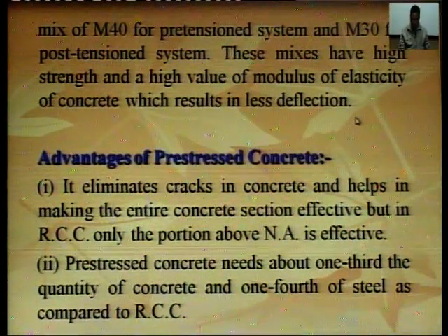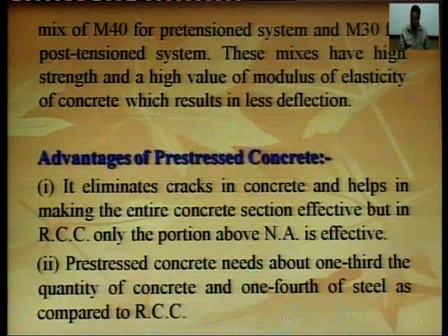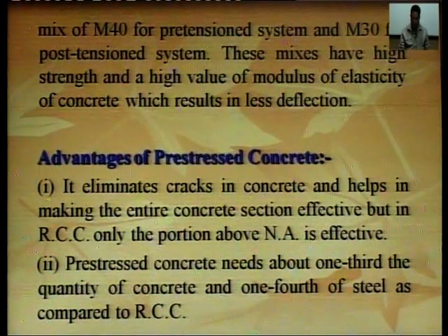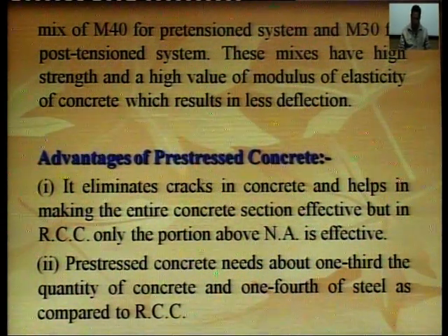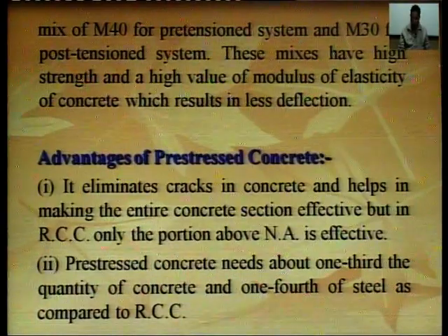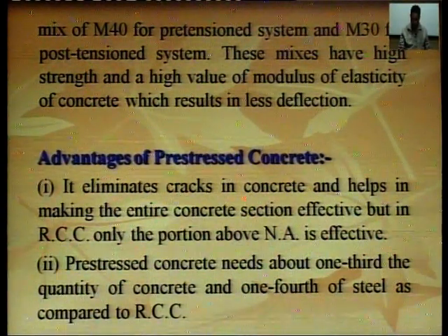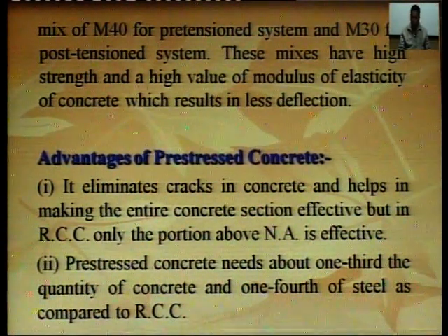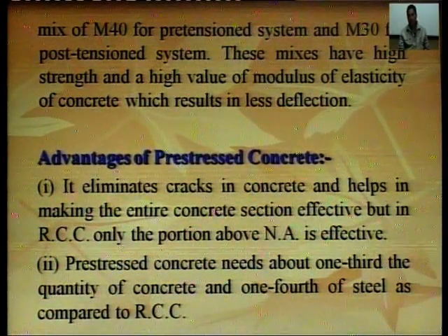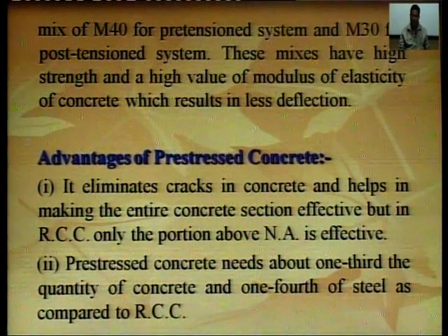For pre-stressed concrete, M30 concrete mix is used for the post-tension method and M40 concrete mix is used for the pre-tensioning method, because these mixes have a high value of modulus of elasticity and less deflection.